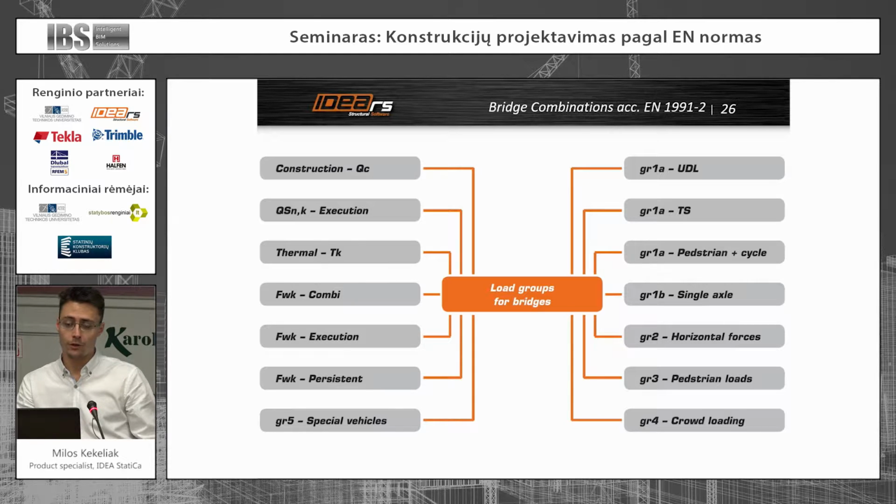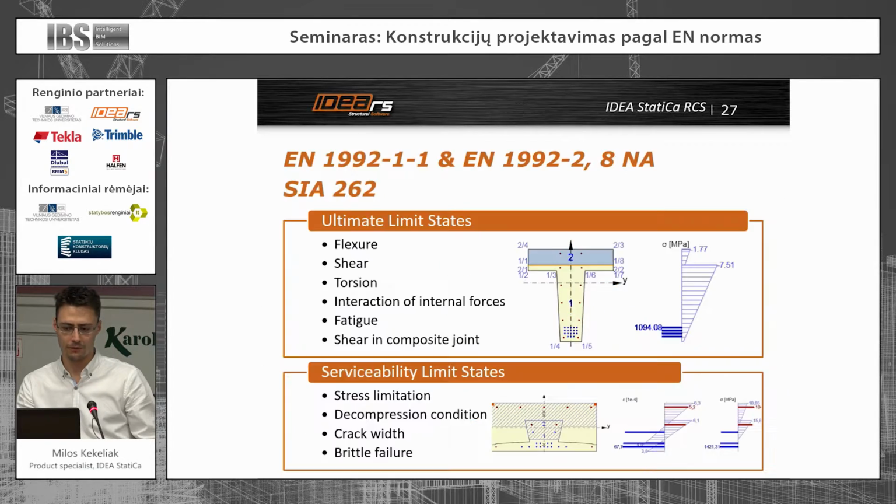In terms of bridge design using Idea StatiCa, it should be mentioned that load groups for bridges are introduced, based on which automatic generation of bridge load combinations is performed. Idea StatiCa provides two main standards: Eurocode and the Swiss code, SIA. Two kinds of limit states can be checked: ultimate limit state and serviceability limit state.